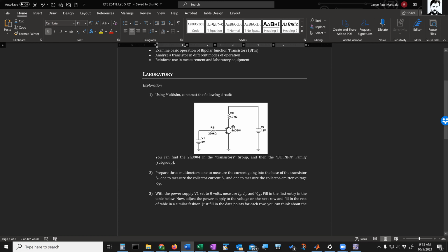And then once the transistor voltage goes all the way down to 0, then it can't drop any further than that, right? You're never going to get a negative voltage there. So the lowest this voltage here could be is 0 volts. So when there's 0 volts across the transistor, that means that there's the full supply voltage across the resistor, right?